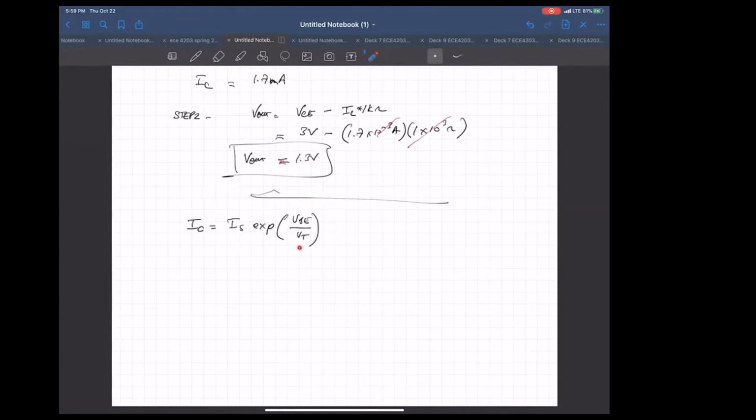So we have a 2-terminal device, and in fact, this thing is the current on the collector, but there's no mention of the collector voltage anywhere in this equation. That means if I plot the collector current versus the collector emitter voltage, it'll just look like a straight line.